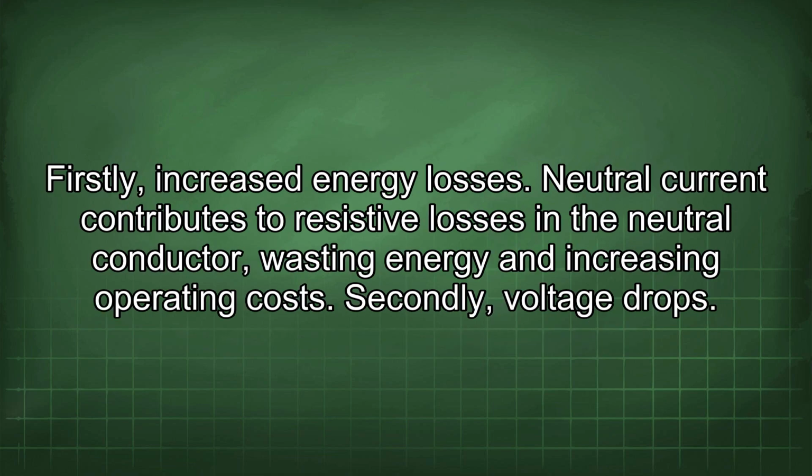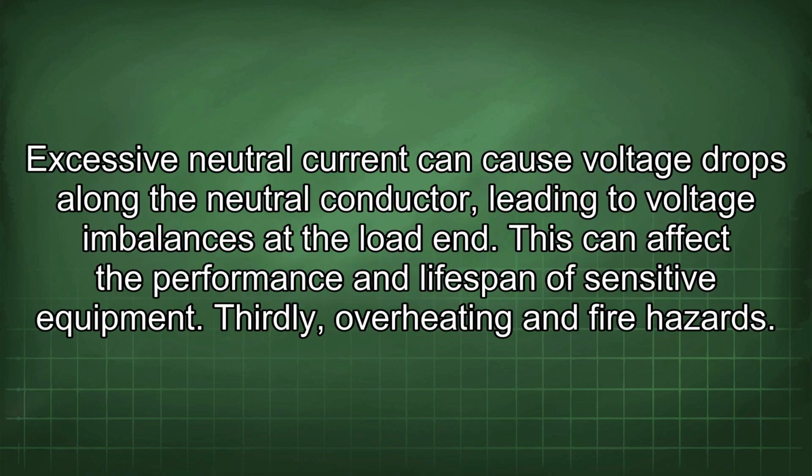Firstly, increased energy losses. Neutral current contributes to resistive losses in the neutral conductor, wasting energy and increasing operating costs. Secondly, voltage drops. Excessive neutral current can cause voltage drops along the neutral conductor, leading to voltage imbalances at the load end. This can affect the performance and lifespan of sensitive equipment.